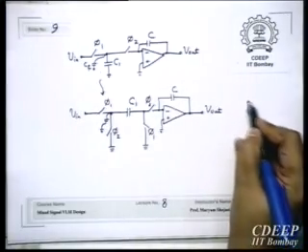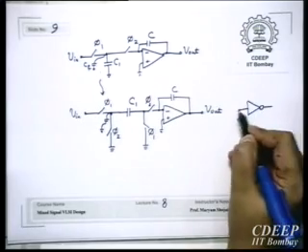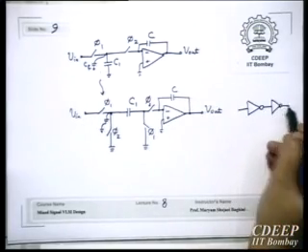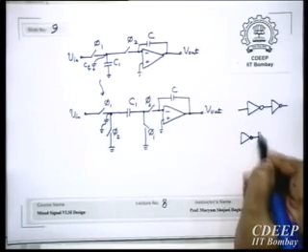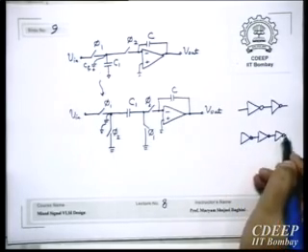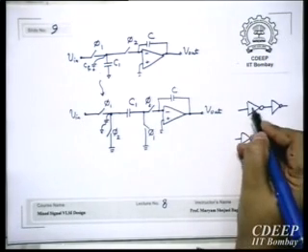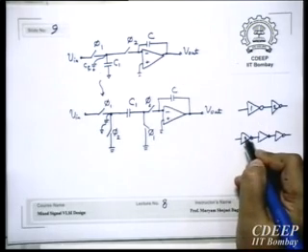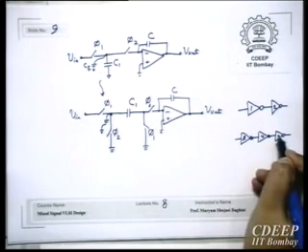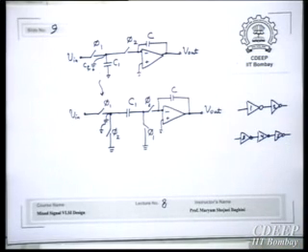You use one inverter, two inverters, and here you use three inverters, okay? But they are not of the same size. Then you adjust so that these two paths will have the same delay. So they are of different sizes. So that's why 1, 2, and then 3, 4, 5. This is one of the bases.